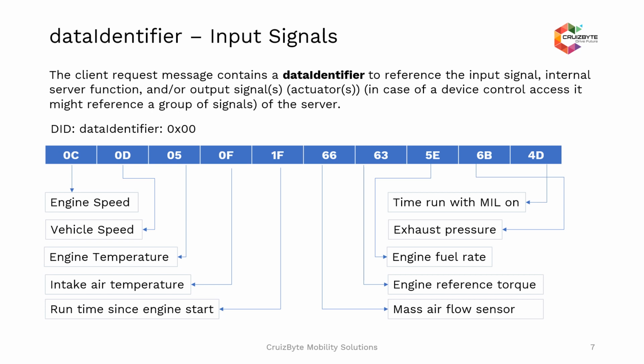The data identifier is nothing but an array consisting of n number of live signals present as part of the ECU. So we can have identifiers 0x00 to 0x100, and inside each data identifier you can save n number of signals, depending on the calibration values available from the ECU software definition.